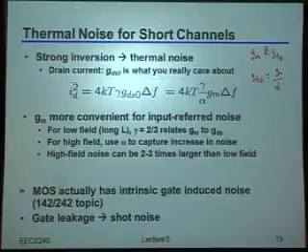That resistance, of course, generates thermal noise. Now, the good news is that this is largely only important at pretty high frequencies. So for most of what we're going to do in this class, that probably doesn't matter too much. But if you take 142, 242, you may spend a lot of time talking about this so-called gate-induced thermal noise, because it could actually have a pretty big impact on the performance of your circuits.